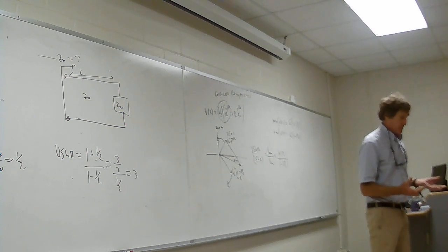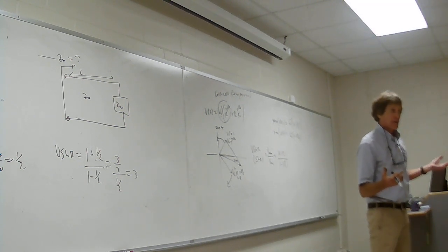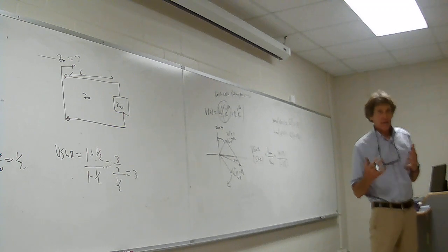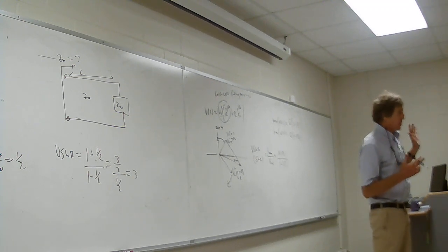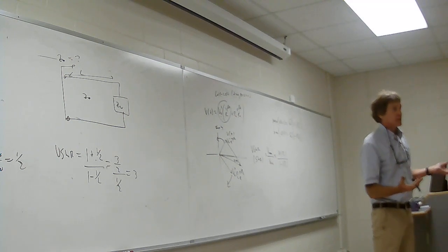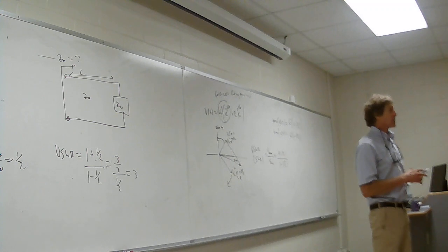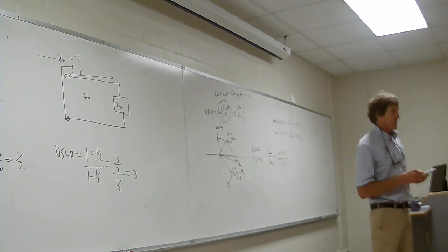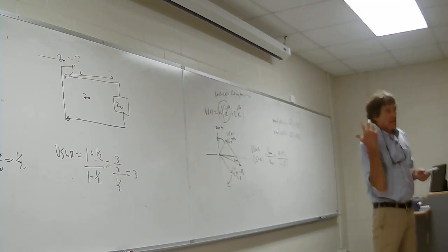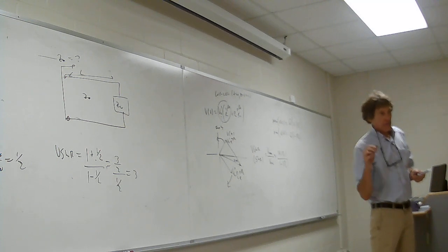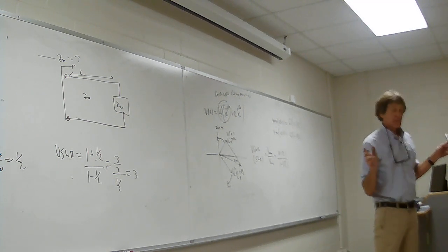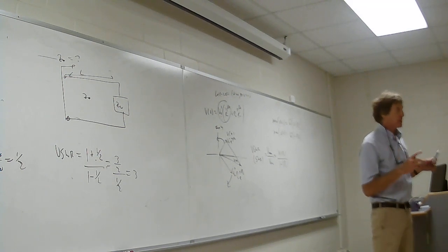So it goes, gets built. I wasn't there. So the antenna comes back, and they get shipped to Ball Aerospace for testing. And they do testing on it. So they're trying to get the antenna pattern and everything. Before going, they look at the standing wave ratio. Now, it was designed for 50 ohms. They have a 50 ohm generator, or feeding the antenna with a 50 ohm source. It should be perfectly impedance matched. Standing wave ratio is 0. Should be 1.